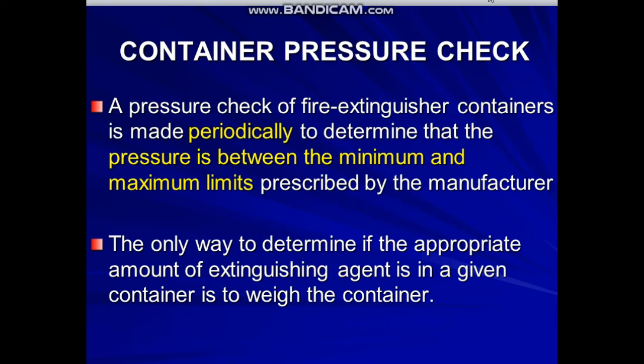Container pressure check. A pressure check of fire extinguisher containers is made periodically to determine that the pressure is between the minimum and maximum limits prescribed by the manufacturer. The only way to determine if the appropriate amount of extinguishing agent is in a given container is to weigh the container.